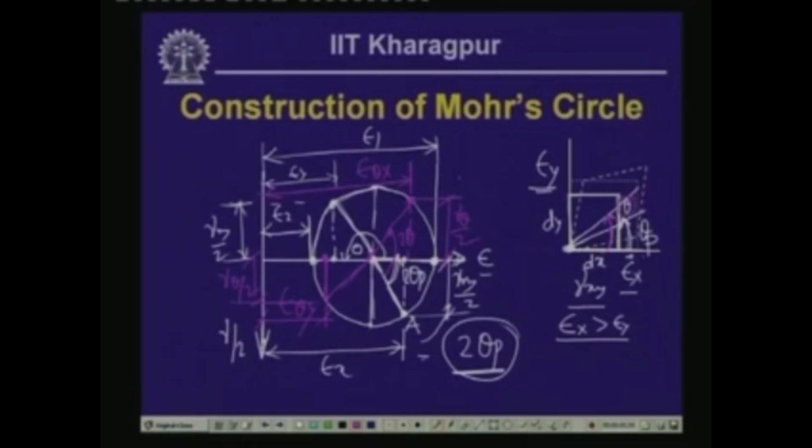So, here also in the Mohr plane we go in the anticlockwise direction by 2 theta to locate that particular orientation, and that is why we consider the direction of epsilon axis and gamma axis in this form, so that the compatibility between the orientations is maintained. And also note that this is the orientation along which the maximum and the minimum shear strains occur, and with reference to this reference plane it will be at an angle of minus theta s, and from here again if we orient by 180 degrees we will get this.